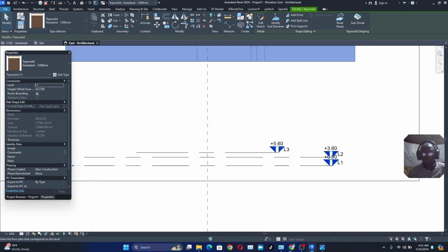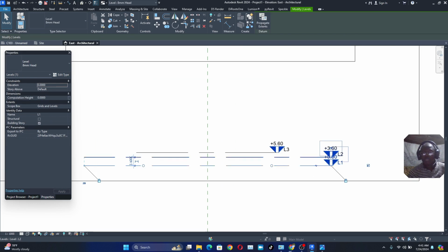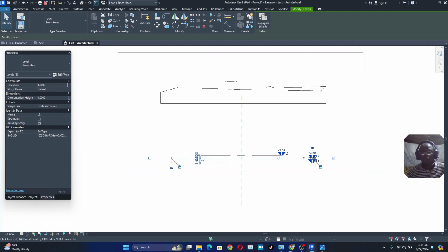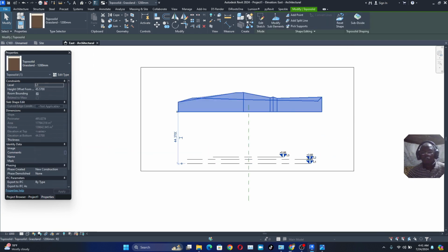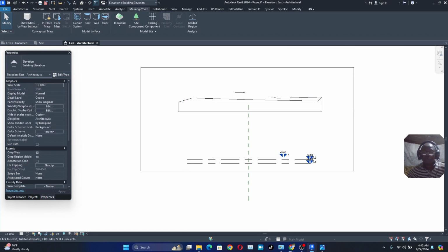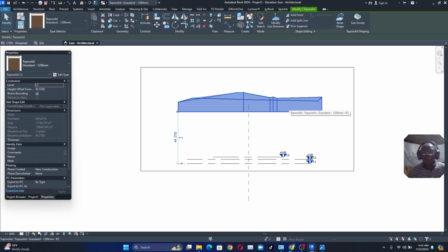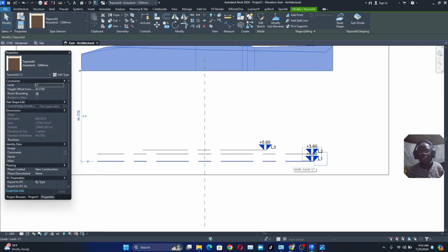This is not the actual level, right? This is a base level that Revit has. So in order to get the actual level of the surface, you try to move these inbuilt levels that Revit has to the actual point, right? And have input into Revit. Wherever this point falls, that is the actual level, or the actual height. So you try to increase this height.